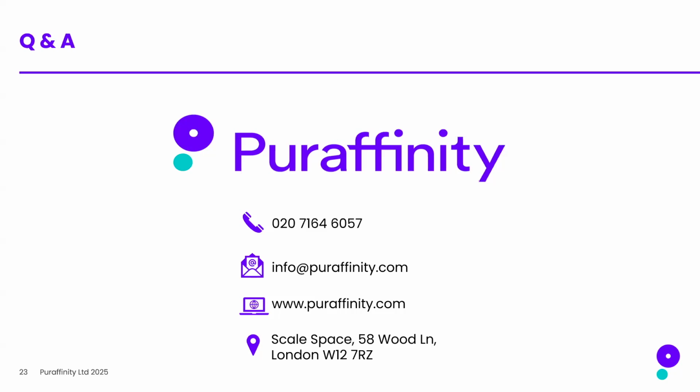Is chlorine affecting the capacity? Is it possible to use the media without backwashing? It is possible to use it without backwashing for sure. Typically with any granular medium, when you first put it online, you want to backwash it to remove some fines and also to stratify the bed, make the little particles go to the top and the bigger ones go to the bottom. But in theory, you could operate it without. Obviously, it does affect pressure drop as well.